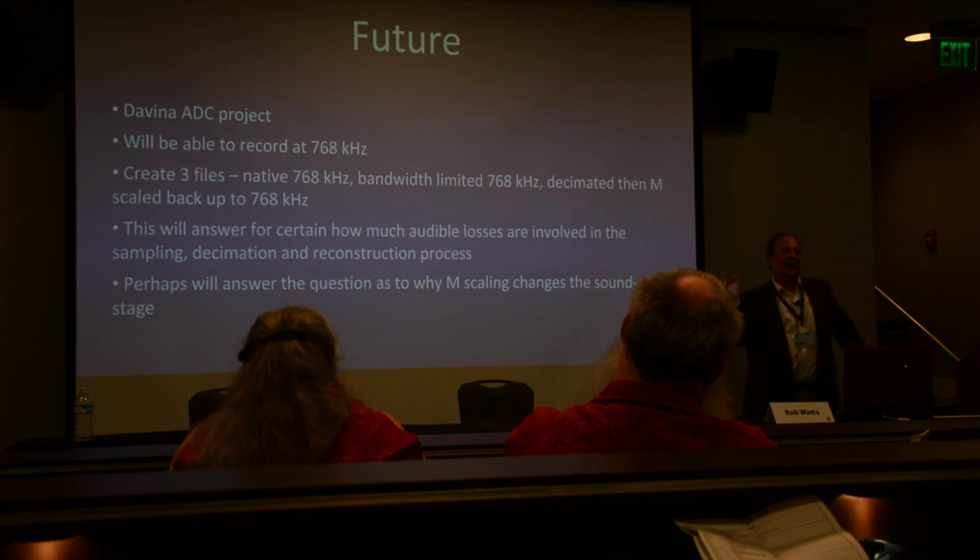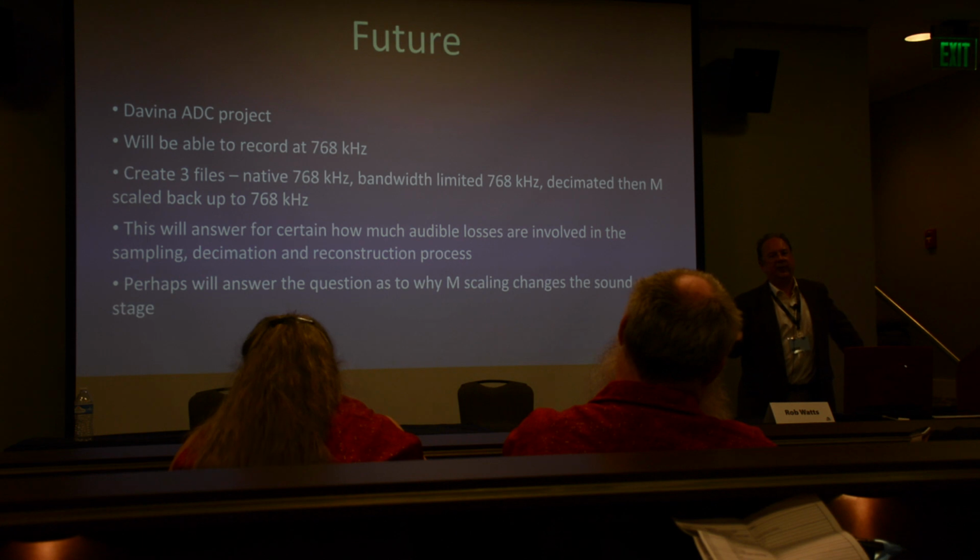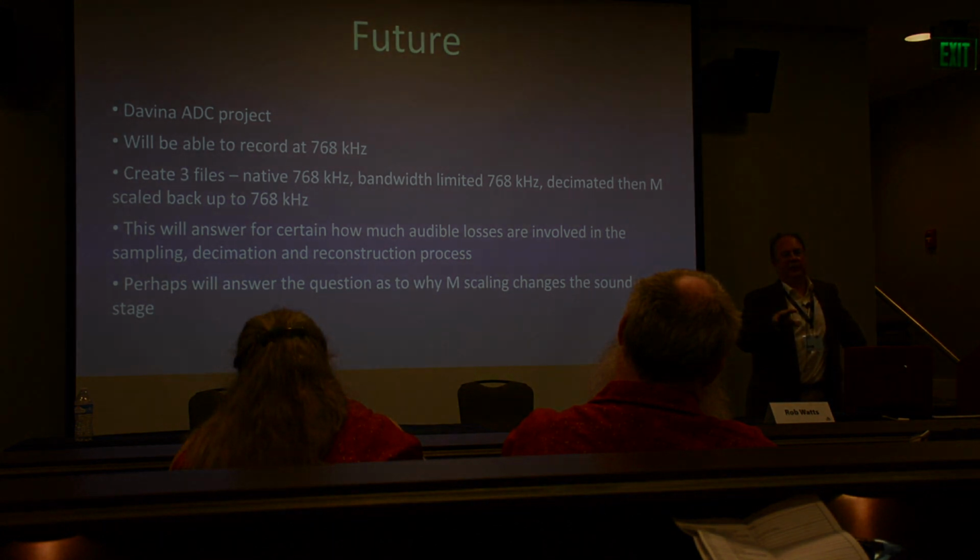So that's another strand. The third strand is noise floor modulation. A to D converters have huge amounts of noise floor modulation, and it's due to the fact, well, it's due to lots and lots of different reasons. Noise floor modulation is crucial in terms of sound quality. And what happens with noise floor modulation is as the signal increases, the noise floor pumps up and down.